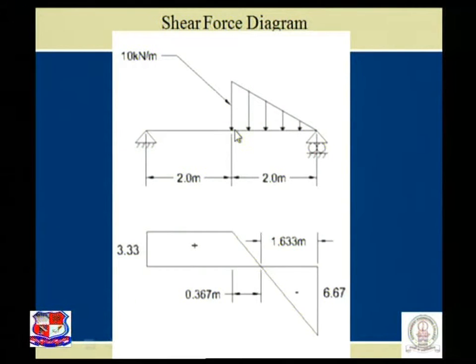Next, our intention is to find out the variation in this region, how my shear force diagram changes. Carefully visualize. The given load is a UVL, hence the variation of shear force has a parabolic nature. So now let us draw for this particular portion.